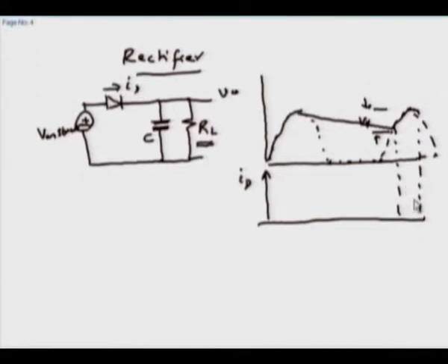Now, the diode in this particular case, in the circuit shown here, can conduct only for an extremely short period. The entire charge which was discharged through the resistance has to be picked up through the small interval in which it is charged, the charging period. Now, if you increase the value of the capacitor, this time period will keep reducing. The ripple will definitely decrease, will become much smaller, but in the same way the peak current would keep increasing.